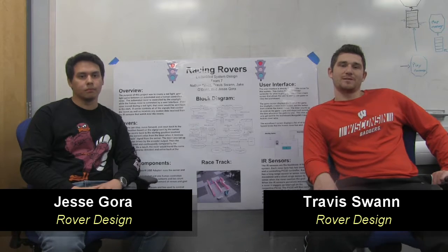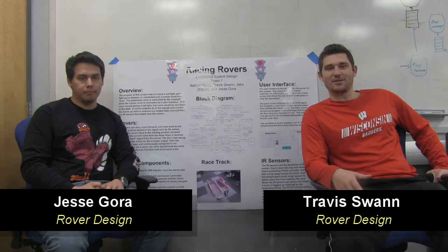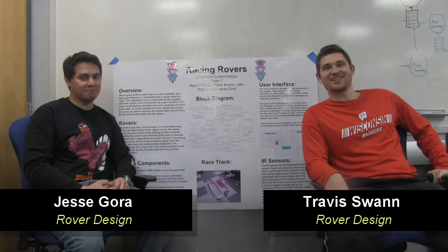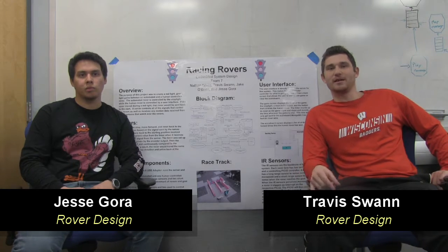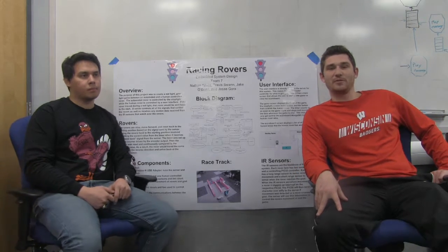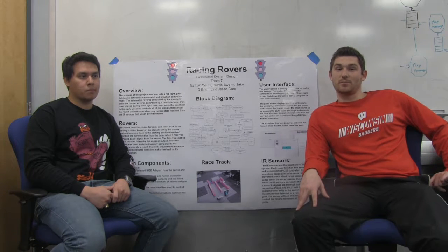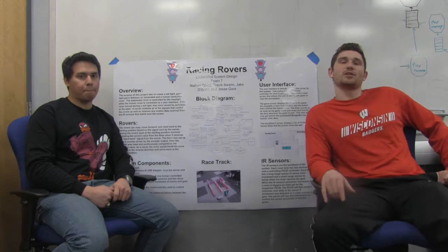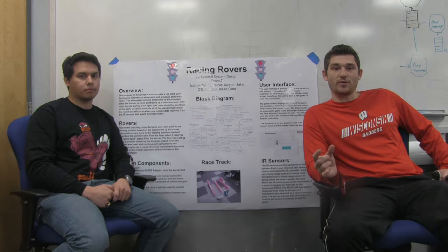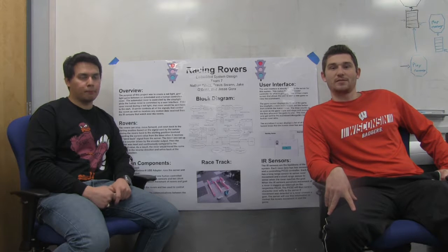My job with the rovers was making sure they could send and receive simple data so that we could control them. So I, being the resident Wi-Fi expert for this project, figured out how we could reprogram them to connect to parent Wi-Fi to send and receive commands. After we reprogrammed the Wi-Fis, we had to set up the UART send and receive on a PIC32, so we got that to work, and then we hooked up the Wi-Fi to one of the Wi-Fi shields that we were provided, and hooked that up to the PIC32s, and it was a simple matter of sending and receiving data.